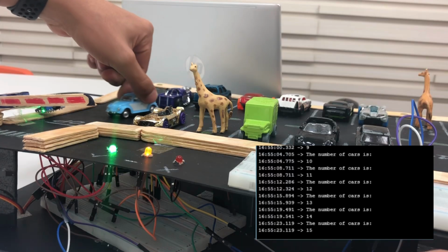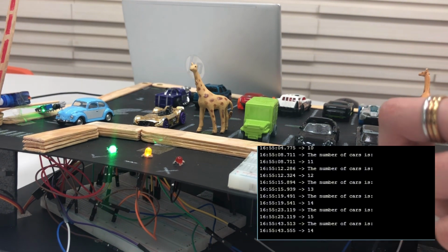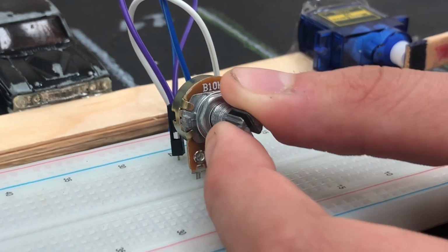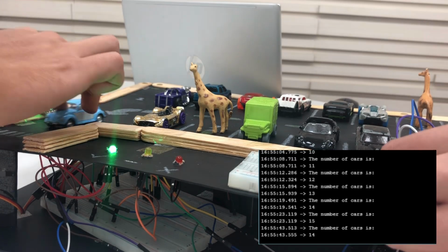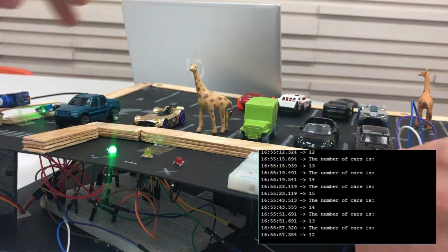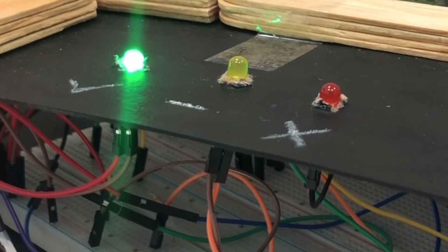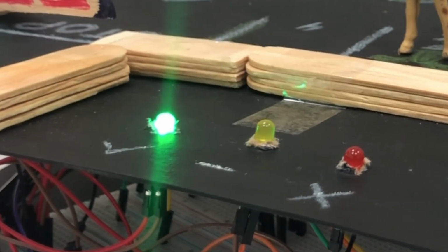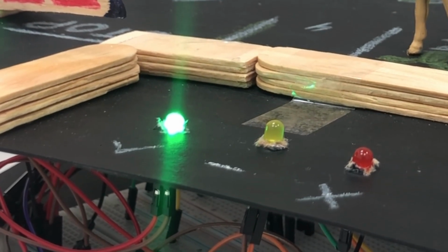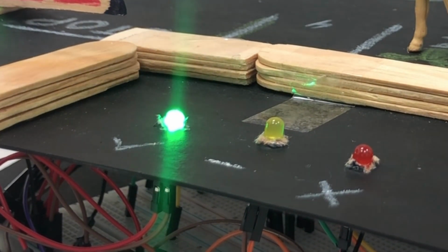After this, in the exit of the car park, the operation is different, because for the car to exit, the sensor must detect a car and the potentiometer must be controlled. We also have 3 LEDs, which ideally indicate the parking status. The green one indicates if there is space for another car. The red one indicates that it is full, and the yellow one varies its intensity depending on the capacity of the parking lot.